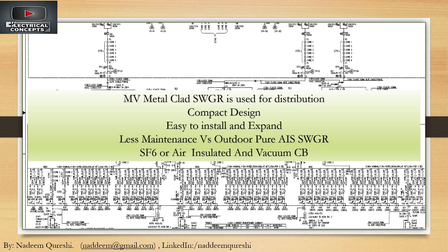It's an indoor type switchgear, stored and installed in a dust-free environment, and it is easy to install like Lego toys. The cubicles and feeders can just be placed adjacent to each other, and then the bus bars can be connected very easily. It is an expandable design with less maintenance versus the pure outdoor AIS switchgear.